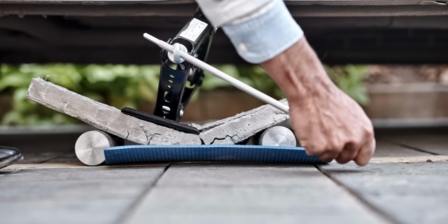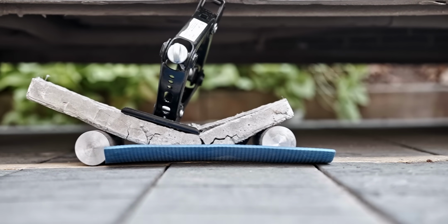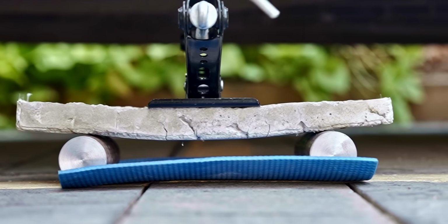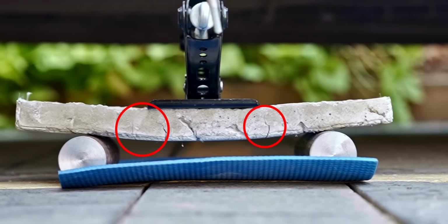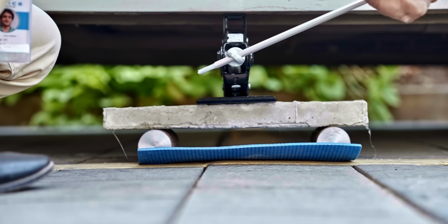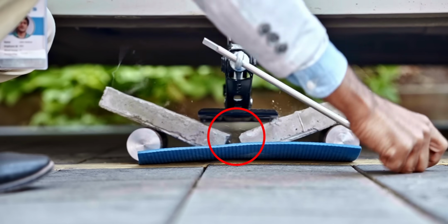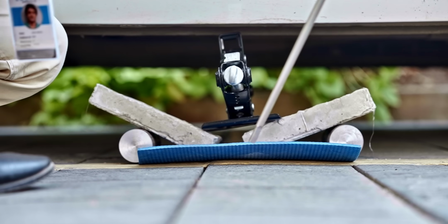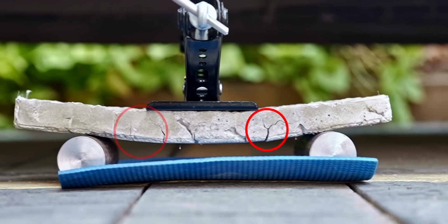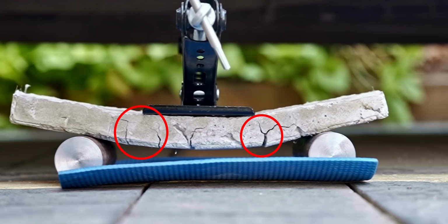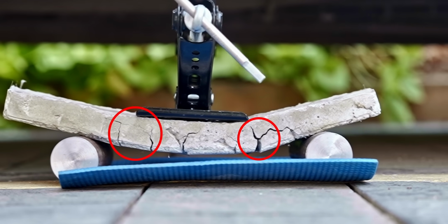Finally, it failed. With the reinforcement, the concrete was able to carry much more weight before it completely failed. Another key observation: with reinforced concrete, cracks form gradually, whereas plain concrete fails suddenly and without warning. In fact, normal concrete is brittle in nature. In short, reinforced concrete can bear significantly higher loads, and when it does fail, it provides clear warning signs.